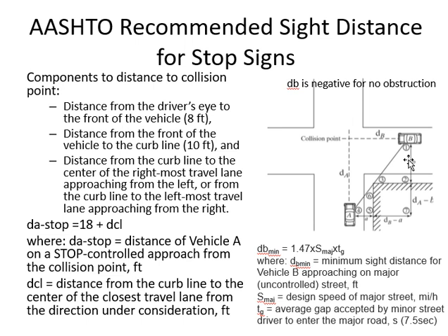Okay? If he cannot see that much distance, if he sees less than that distance, then it means that whenever he decides to go, he is deciding on something which he cannot see. Okay? So in order to go safely, he should have a gap of this much, and in this much time, the car covers this much distance. So his actual sight distance should be equal to this or more than this. If it is less than this, that means whenever he decides to go, he is unsafe. Clear? Okay. Any questions? Okay.